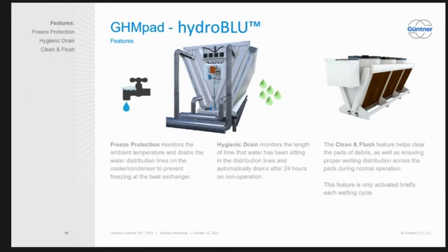So no water treatment is recommended, but it's not going to void any warranty if I throw some filters on there, just trying to do better for it, right? Yeah, because you're just trying to improve the water quality. The only thing I would say is make sure that the water pressure to the unit is around 30 psi. That's kind of what we're looking for. Is that how you're figuring out?